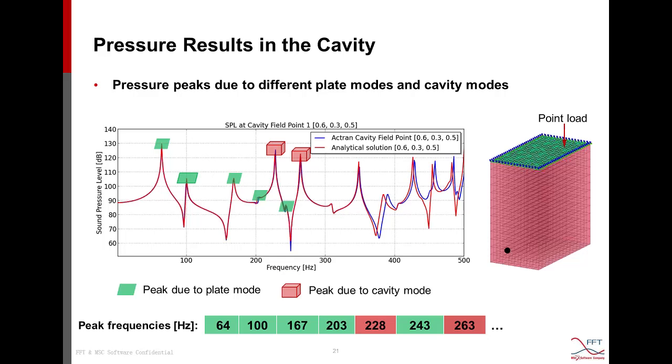As for the results, I will not launch the computation now. It has been launched previously, and we obtained different results for the 3 different models. On the basic model with little damping on the plate, but no damping in the cavity, we see this curve for the sound pressure level at that microphone point.